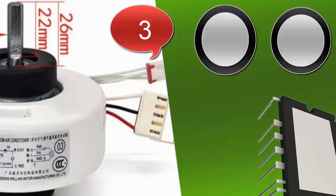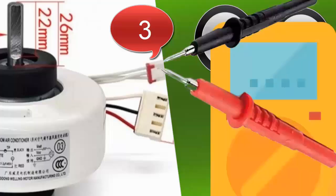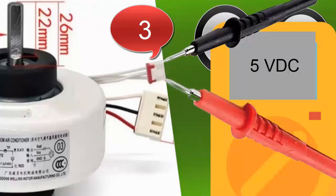How to identify the wires? To identify the power and ground wires, energize the control board and use a multimeter set to DC voltage. Place the red and black probes of the multimeter on each pin of the sensor. When you read a steady 5 volts, the pin touched by the red probe is the power supply. The pin touched by the black probe is the ground. The remaining pin will be the signal output.